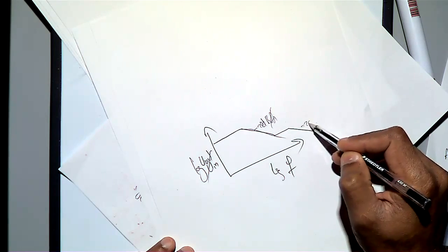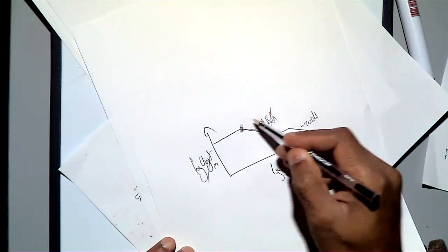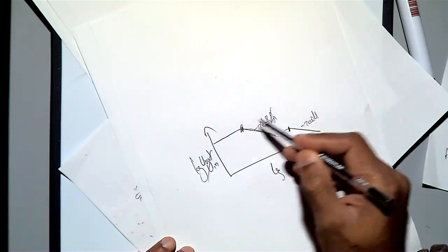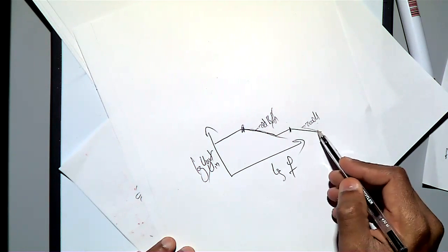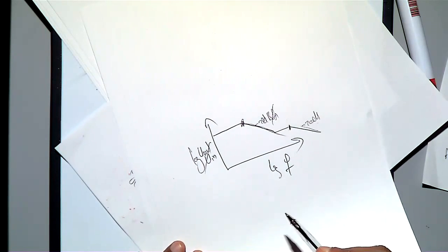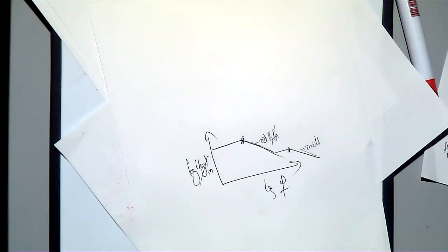That's the reason we identify the poles. How many points are there in your frequency response where your gain will decrease by minus 20 dB per decade? So that's the entire point of finding the poles in the circuit.